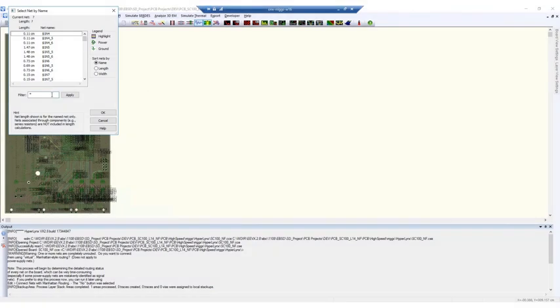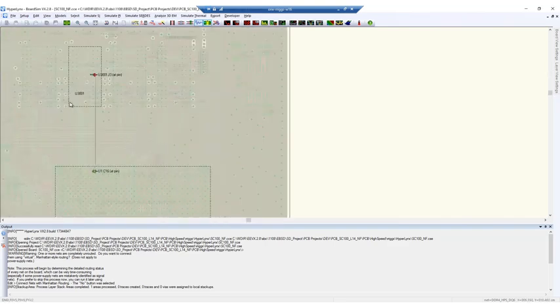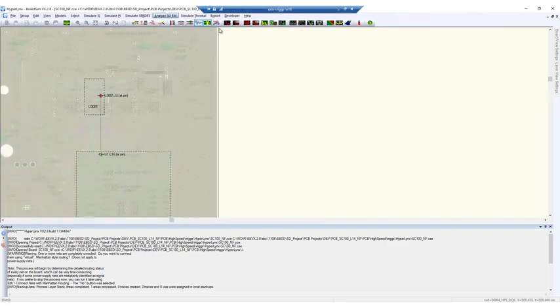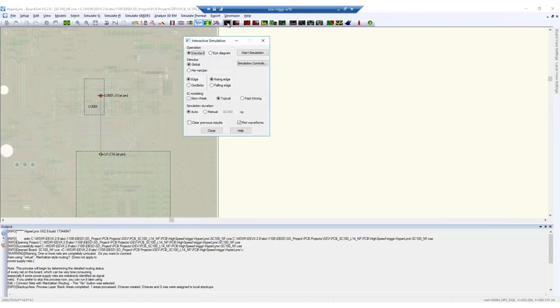Hi again, this is Rory here to do the final sign-off for signal integrity on our design. Since we have done the automated checks with Hyperlinks' DRC and the power integrity sign-off with DC drop and decoupling analysis, now we need to run a more advanced analysis with the DDRX wizard to verify our DDR4 memory.